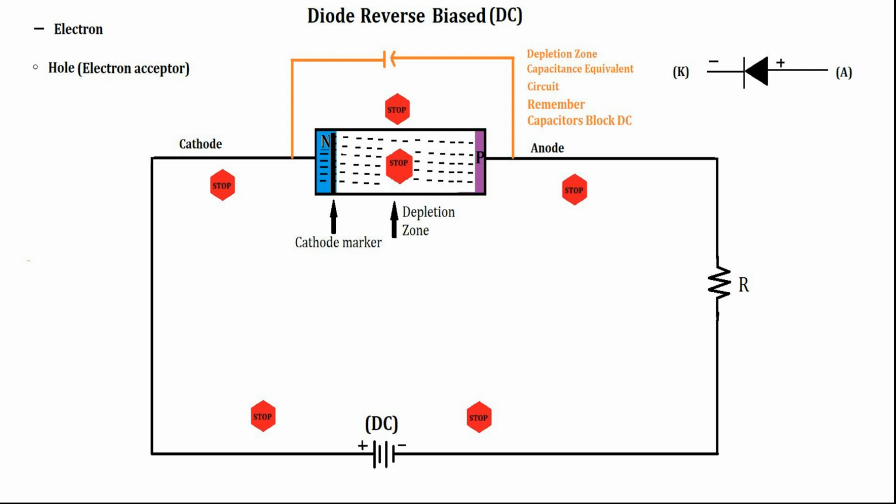The depletion zone widens as the holes fill with electrons that can't get through the N material. It works kind of like a wall because like charges repel. In this case, all those electrons on both sides of the depletion zone resist current flow. The diode now looks somewhat like a capacitor, and capacitors block DC. So now I've gone from a switch to an open circuit.